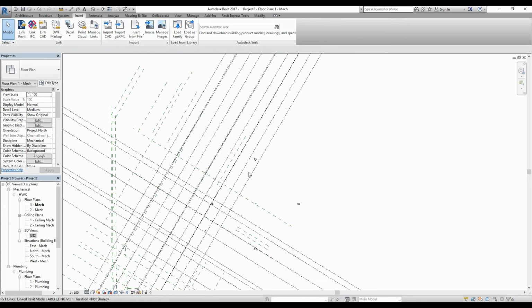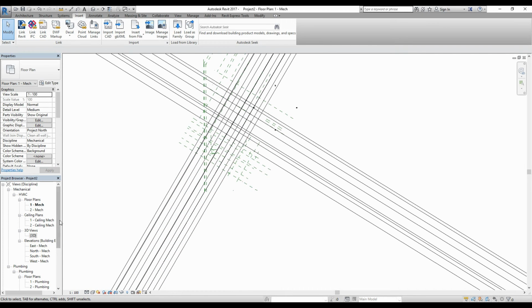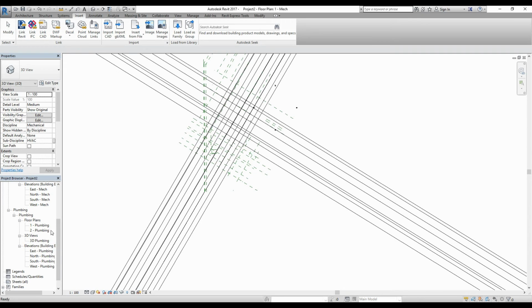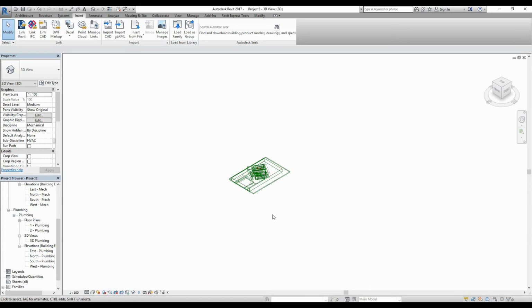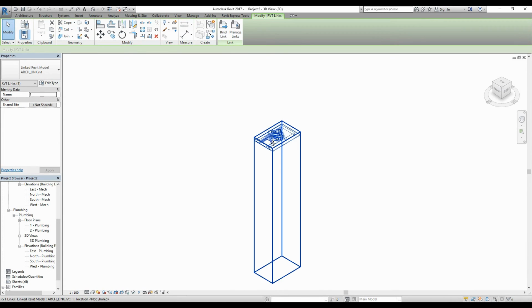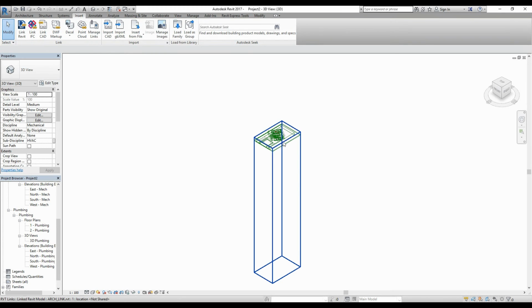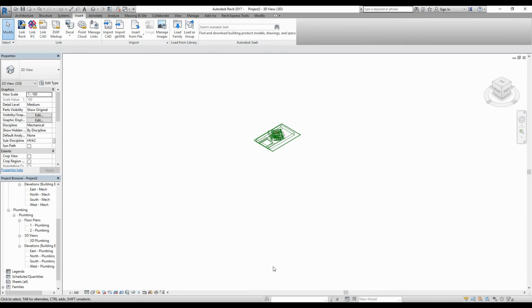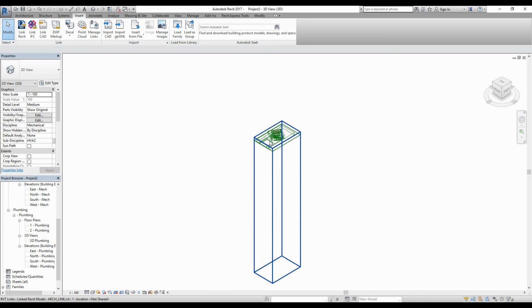So what we can do is we'll open our 3D view, and I'll give you an idea what we're looking at. So I think the issue is that the models are way up here and our level starts way down here. Usually metric levels start at 100,000 above ground, above zero, is usually the starting elevation.